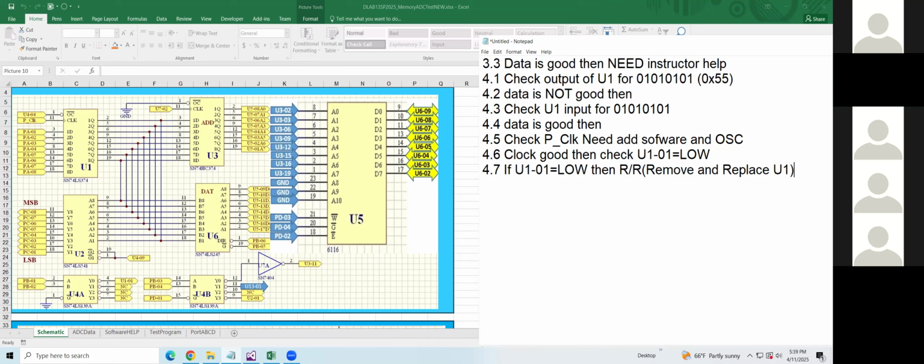However, this is in the lab, there will be a minor difference. For example, you see U1 pin 3 at logic 1, then U1 pin 2 has to be at logic 1, right?